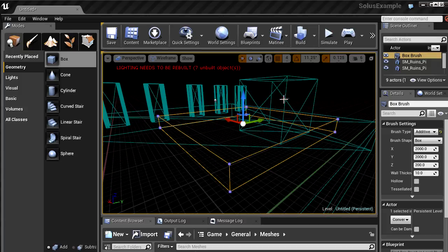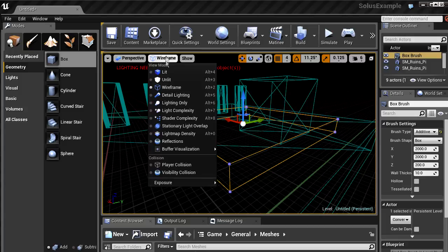And they can't do as much as real models. So this is a much more limited system. So this should only be used really for the most basic shapes. You can see you have a cylinder here and you have a sphere here, but the cylinder and the sphere and the cone, none of that will work really well. So I would, if I were you, completely avoid all of these and just stick to basic boxy shapes. Otherwise you're going to run into problems.